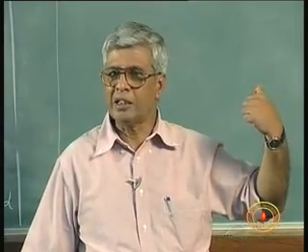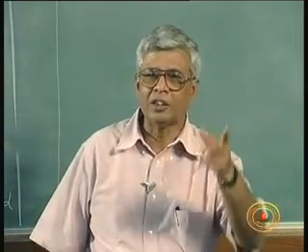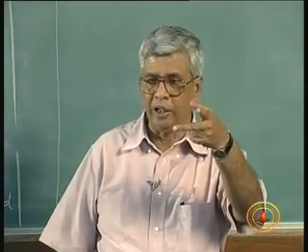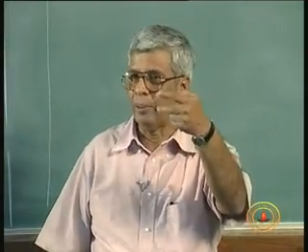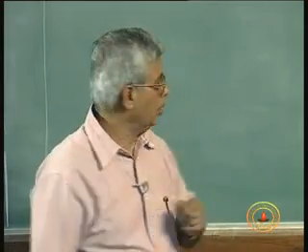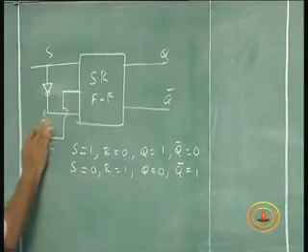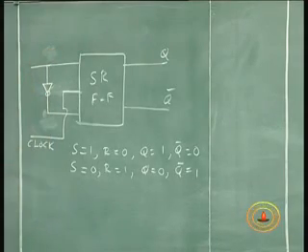So this is a simple flip-flop where I have removed the condition of two inputs being required to store one bit of information. So this need not be called SR. What is the need for calling it SR? Because they are always going to be complements. I can as well call it a D flip-flop. D for data. It stores a data bit. A bit of data is 0 or 1.